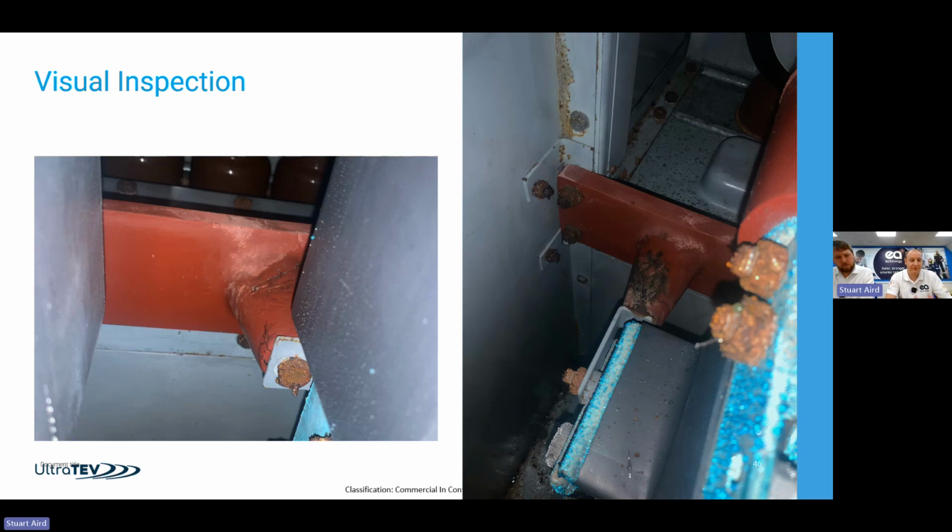So if you've got this type of equipment, any air insulated switchgear really in a high humid environment, you will start to get partial discharge activity. It will increase it, and reduces the dielectric strength of your air. You start getting dew points on it and things like that. So that leads us into another case study where we're talking about the effects of humidity. Well, Gareth's going to talk about the effects of humidity.